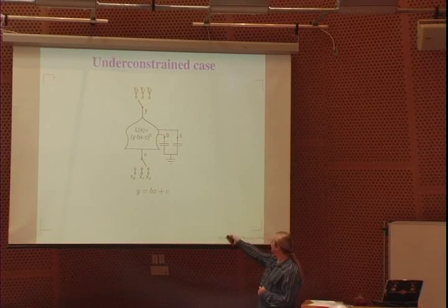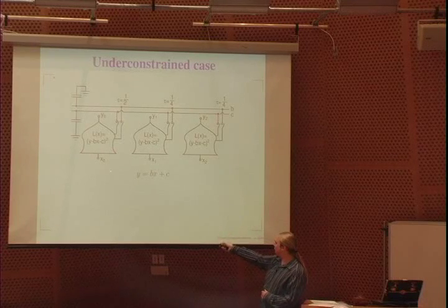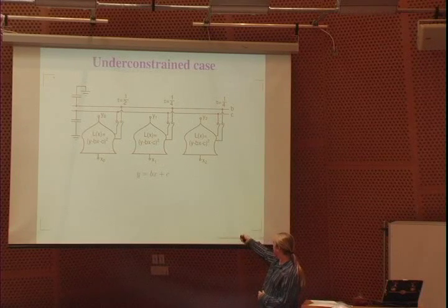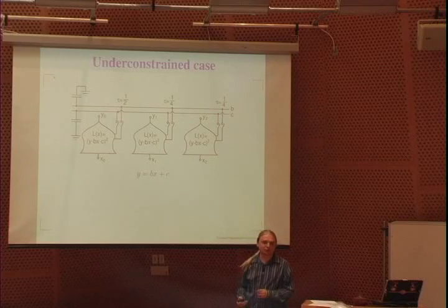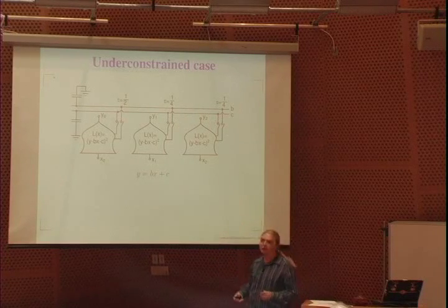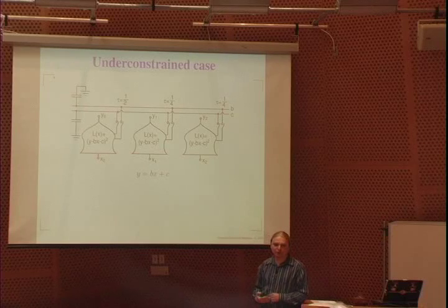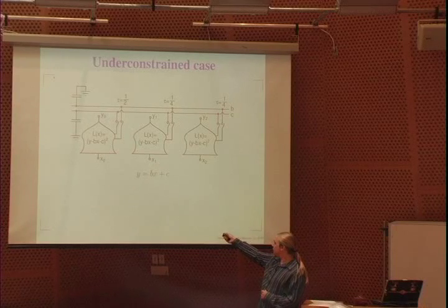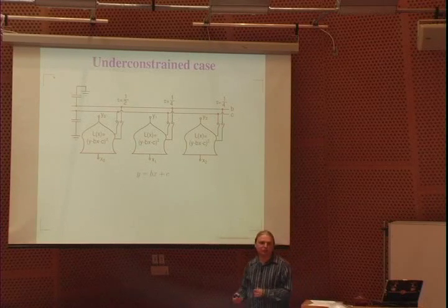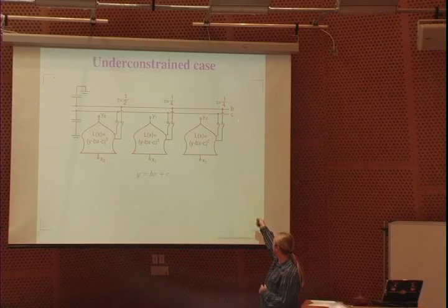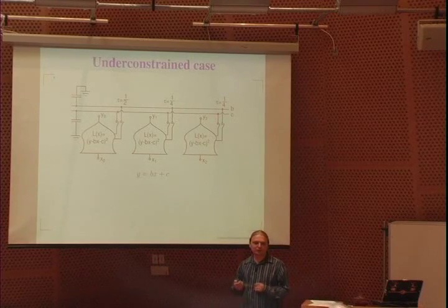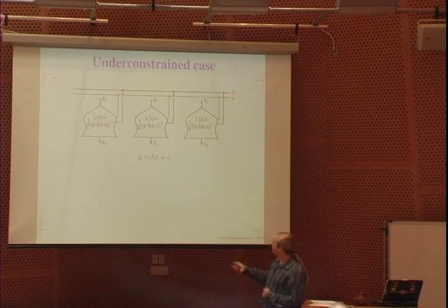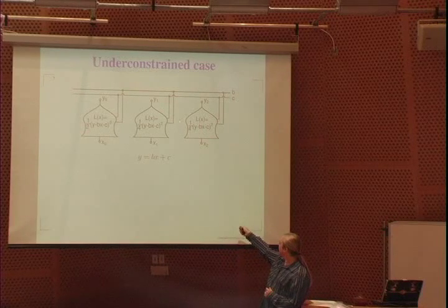That's the same as if we had three blocks, one of them looking at y0 and x0 all of the time, one of them looking at y1, x1 all the time, one of them looking at y2, x2 all of the time, and we just switch those blocks onto the nodes b and c with the same duty cycle, 1/2, 1/4, and 1/4. Now, if we do this switching adequately quickly, so that the time constants of the switching are much faster than the time constants of the capacitors, so that between each switch, b and c changes a very small amount, this is the same as having three constraint blocks connected to b and c all of the time, just outputting half of the current, a quarter of the current, and a quarter of the current.